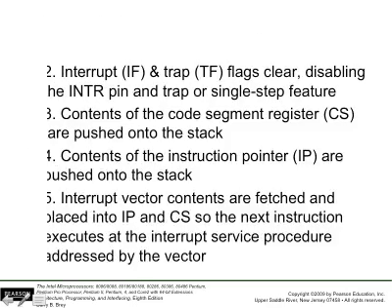If one or more of these conditions occur, the microprocessor will do the following things. It will push the flag register to the stack because it knows that it's going to handle interrupt service routines. In order to be able to get back to the main program properly, it has to save the flag register onto the stack.